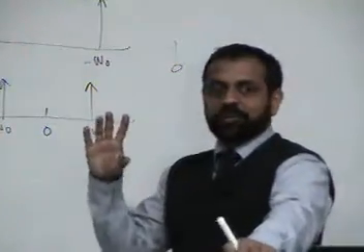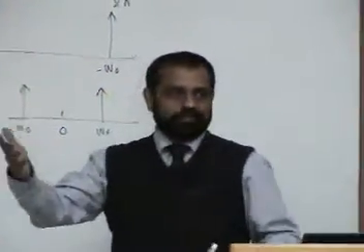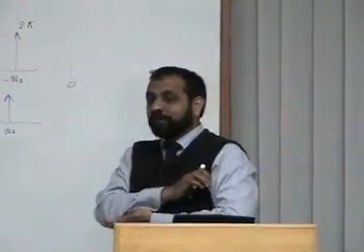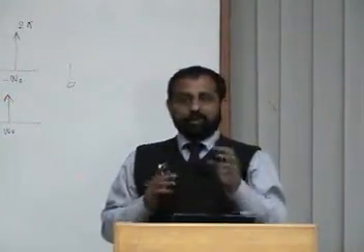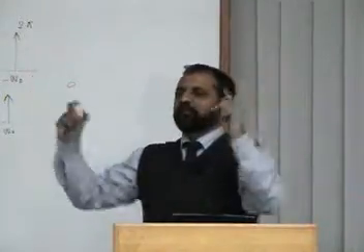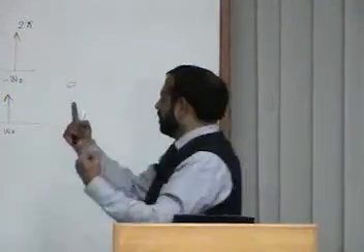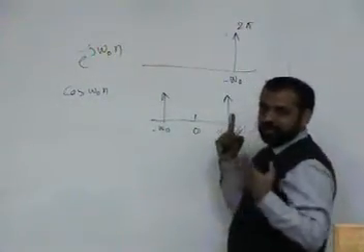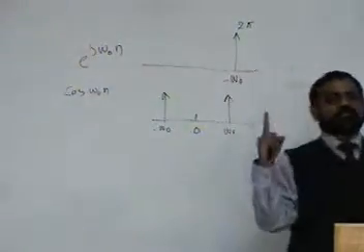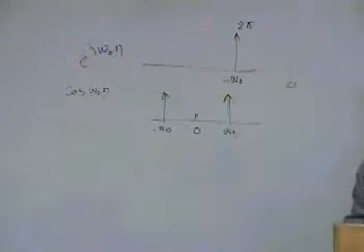There are transforms called the cosine transform, the sine transform, and so on, that tell you that these cosines are there in your signal. But a Fourier transform tells you what type of complex exponentials are there in your signal. That's why once you put a cosine, you are going to see two of these impulses. If you put a sine, again you see two. If you put an exponential, you only see one, because there is only one complex exponential.